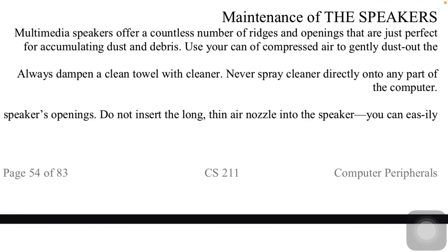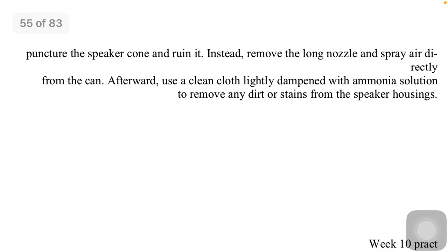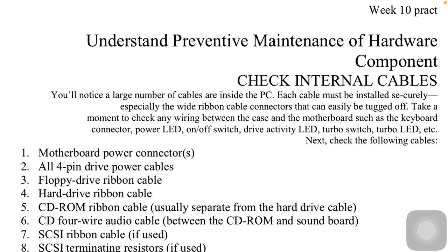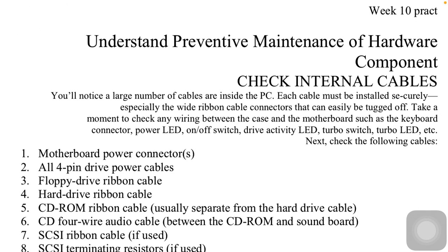Then the cone of a speaker can be dusty. You clean it gently. You can use ammonia solution. Clean it gently so that you don't perforate the cone, because when the cone is perforated, the speaker will not do well anymore. Okay? Understanding preventive maintenance of hardware components.